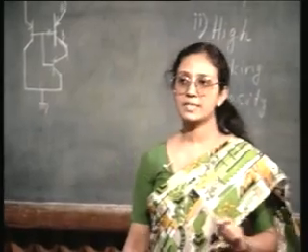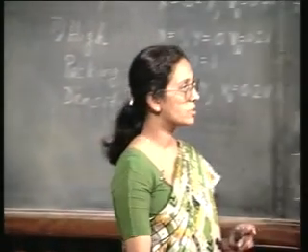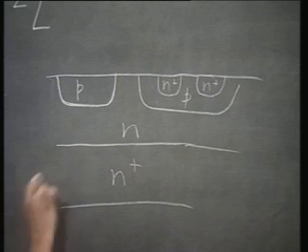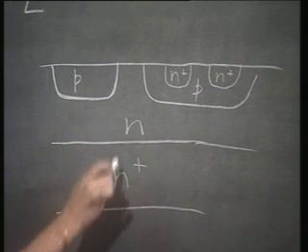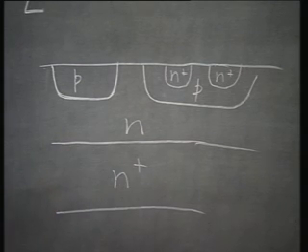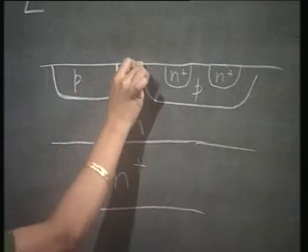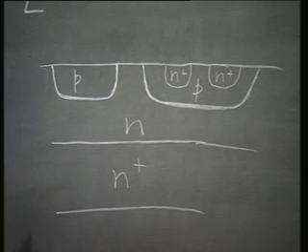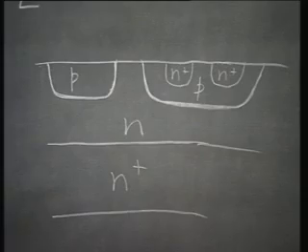Okay, now let us look at the basic I square L circuit from the technological point of view. I have started with a substrate called N on N plus, that is, I have N plus as the bottom layer on which an N epitaxial layer is grown. I have used this N on N plus epitaxial substrate. Now, in this I have diffused two P regions. So, you see I have a lateral PNP transistor. This is going to be my current source.